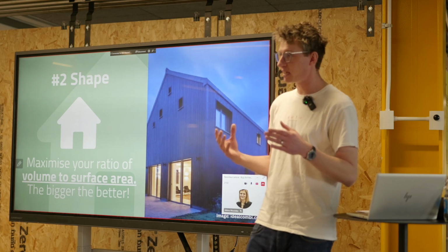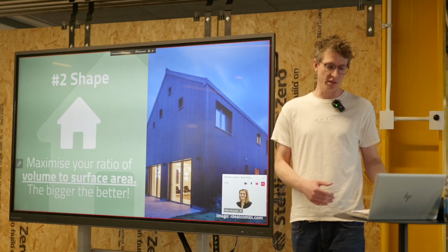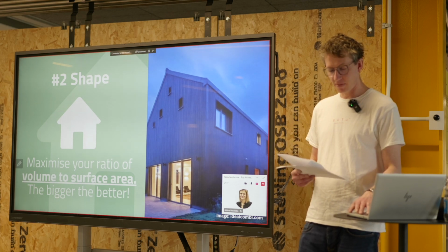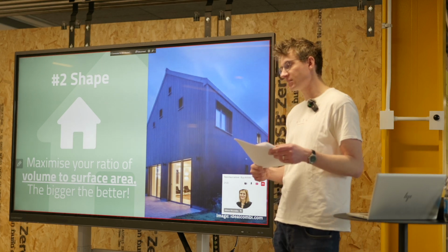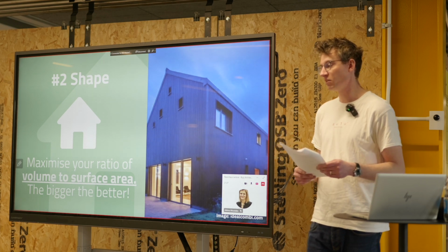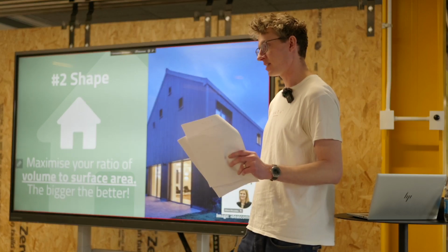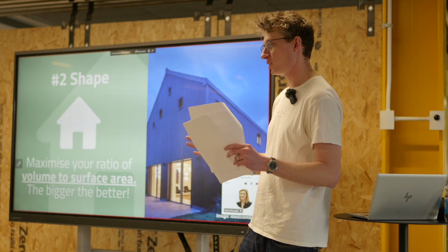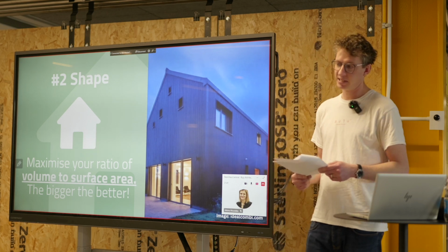Sometimes it's actually slightly beneficial to have a slightly elongated south facade because you're getting more solar gain through that elevation as well. Another thing that I was going to touch on was the National Space Standards. I'm not sure if you're aware of that, but if you're doing any residential design, there's a set of national space standards to tell you how big properties should be, or what their minimum standards should be as well. So whenever we're master planning a site, that's almost part of this. At this stage, when we're thinking about the shape of the building, we look at those national space standards to work out good sizes.